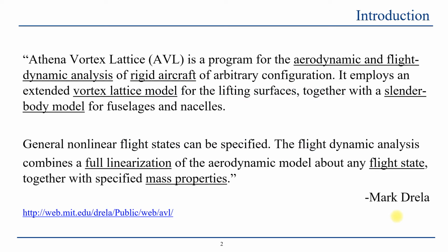So AVL stands for Athena Vortex Lattice, and AVL is a program for the aerodynamic and flight dynamic analysis of rigid aircraft of arbitrary configuration. It employs an extended vortex lattice model. Remember that it is an extended version of the VLM or vortex lattice model for the lifting surfaces, together with a slender body model for fuselages and nacelles.